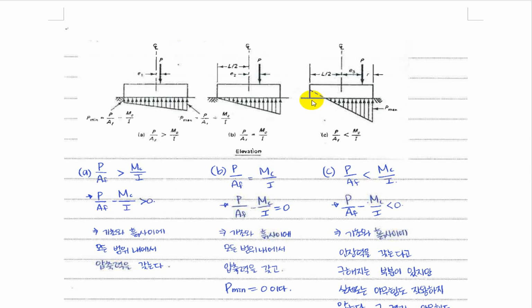We have to introduce a bigger size of foundation to see if the Pmax, the soil bearing pressure, is less than the allowable soil bearing capacity.